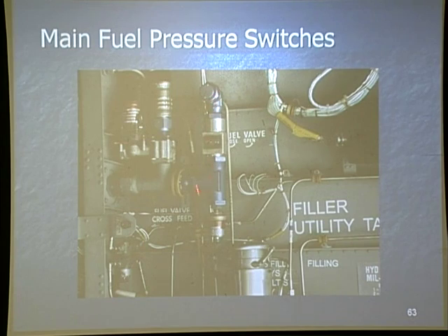How about my defueling system? Is my defueling system associated with both sides of the aircraft? No. Nope, only my right side. So this is my right side of the aircraft. This manifold right here, if you could see right here, fuel would be going up to the engine on that side of the manifold. The crossover line comes through here, and we're going to show you.